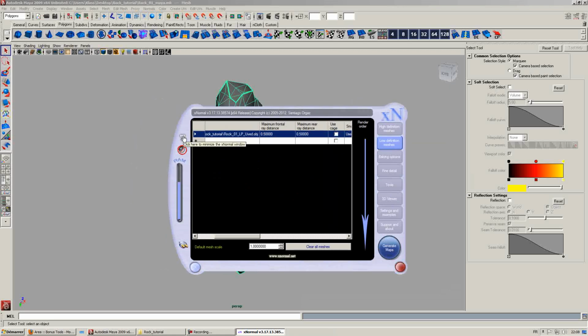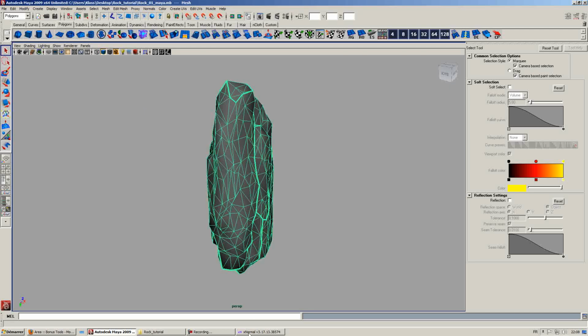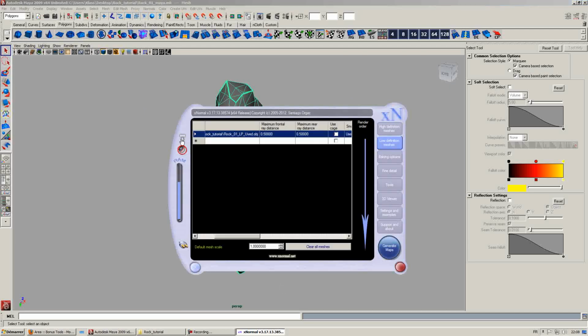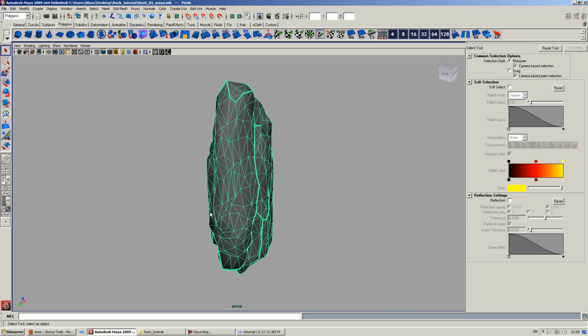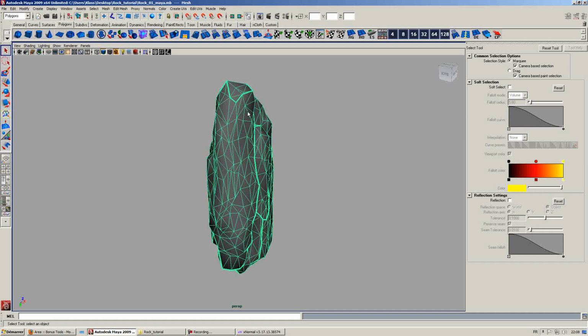Technically, since we're not using a cage for rendering the normal and ambient occlusion, this is going to give you the optimal values for where the cage is going to be pushed outside and the one that's going to be inside, in order to capture all the detail from the high poly mesh.